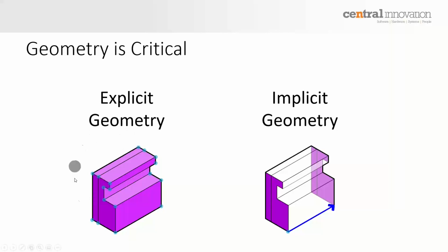Some objects inside Archicad use the explicit geometry method to begin with, but it actually depends on the object, since in the GDL scripting code, you can actually describe explicit or implicit geometry. Now, when it comes to the exchange, you will actually prefer, in this particular case, to go for implicit geometry, which is then going to be able to be reused inside the software.